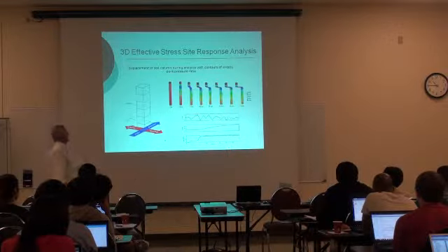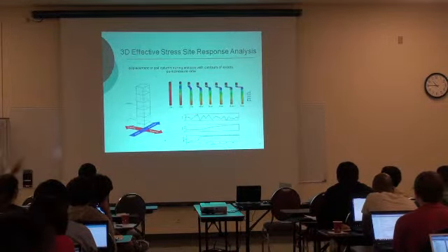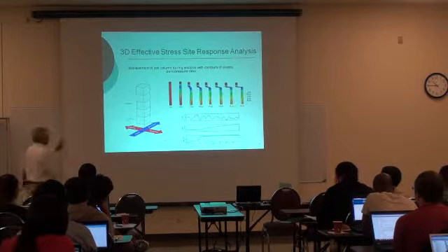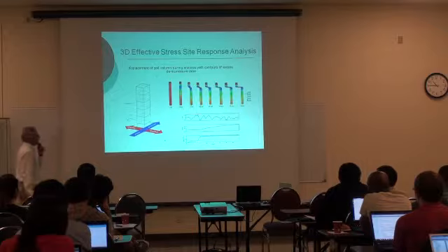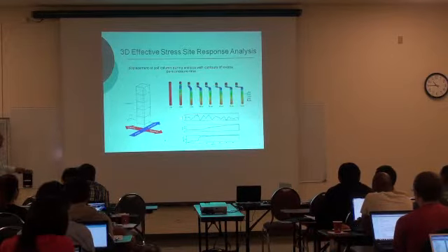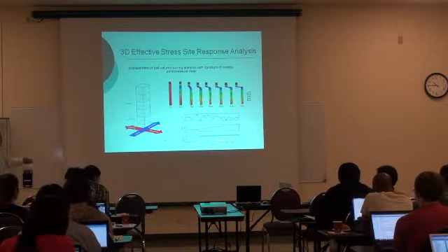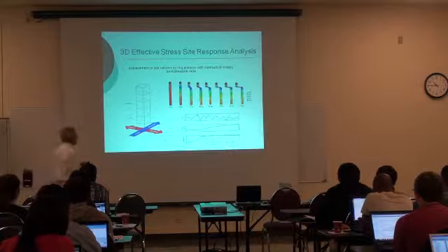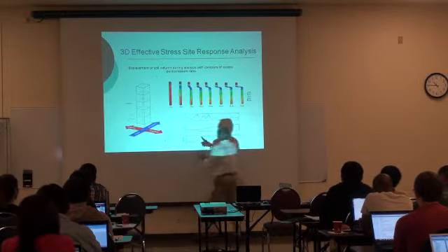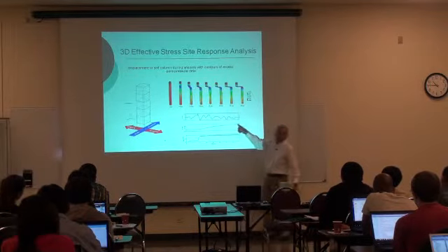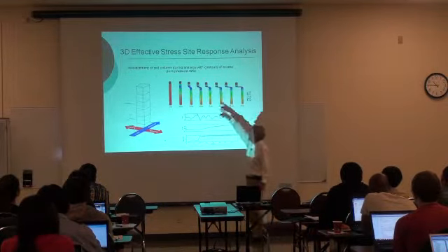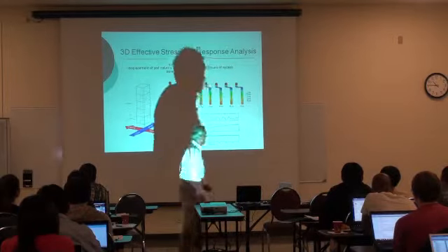So how to characterize the response? Now you are in the 3D analysis, something that many codes cannot do. Now you are in the area where OpenSees becomes important. So here is the displacement in the red direction, and this is the displacement in the blue direction. Notice that not much happens until the pore water pressures are so high that the soil liquefies, and then you have a lot of deformation. And these are just snapshots of the displacement.